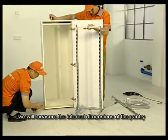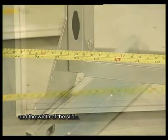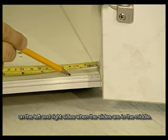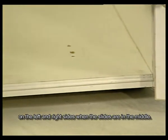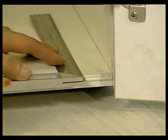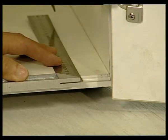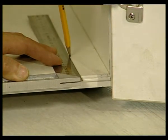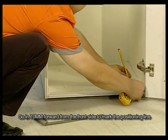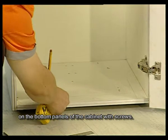In the next step, we will measure the internal dimensions of the pantry and the width of the slide. Calculate the slide line position of the slides on the left and right sides when the slides are in the middle. Go in 70 mm forward from the front side to mark the positioning line, and you can secure the slides on the bottom panels of the cabinet with screws.